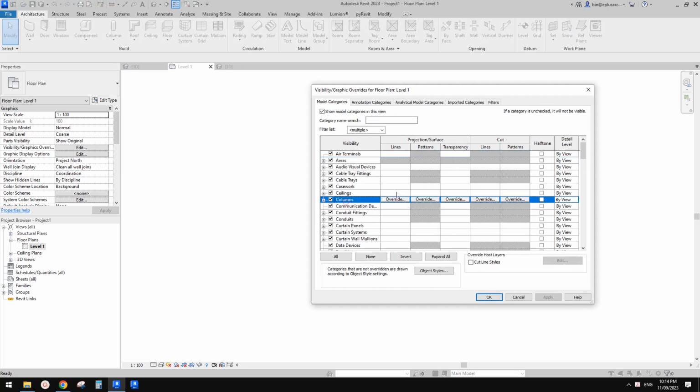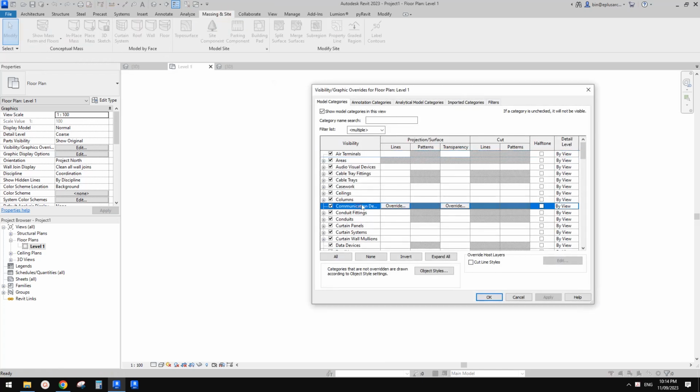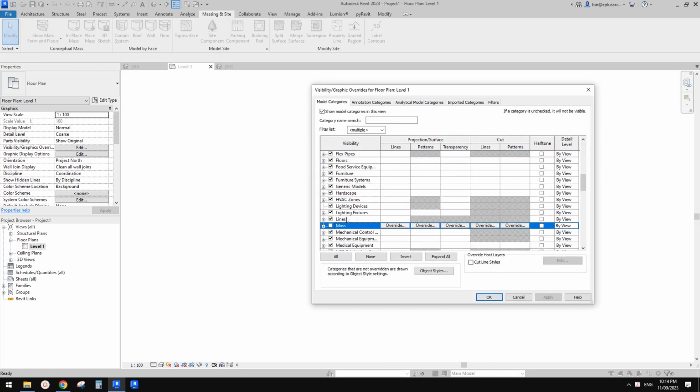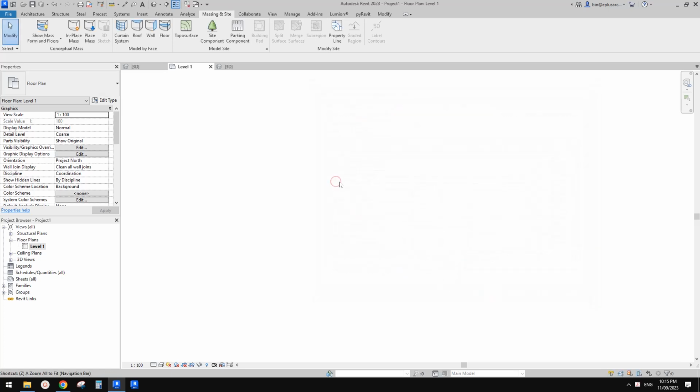So usually, I'll go check here, not here, VV, mass. Because usually a floor plan, so this is a floor plan, a default setting, the mass is hidden in this VG setting, so you just need to turn it on. Is it there? Still not there?